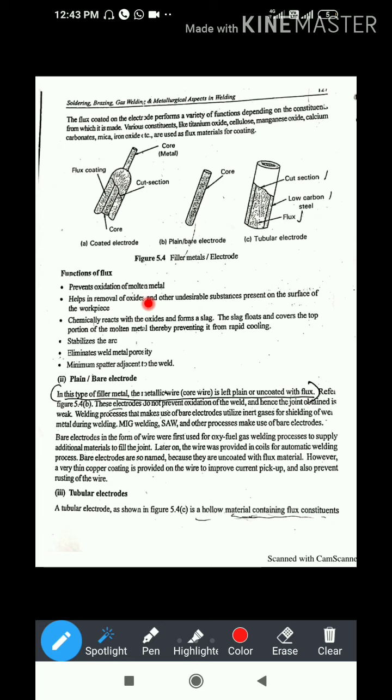At the bottom, where the molten metal is, it doesn't come in contact with the outside atmosphere or environment. It maintains its temperature and cools according to its temperature. It doesn't come in contact with the outside temperature because the slag covers the liquid metal at the top, due to which the molten metal cools down slowly and gradually, as per its own property or its own nature.